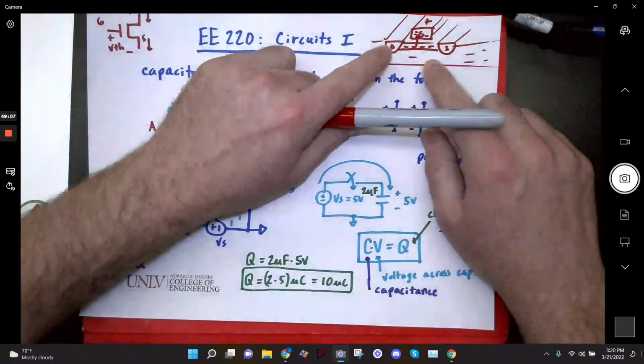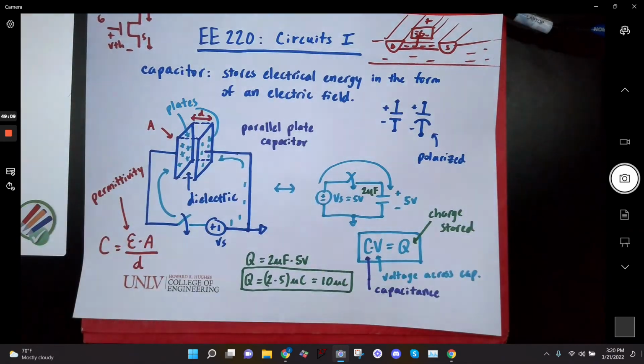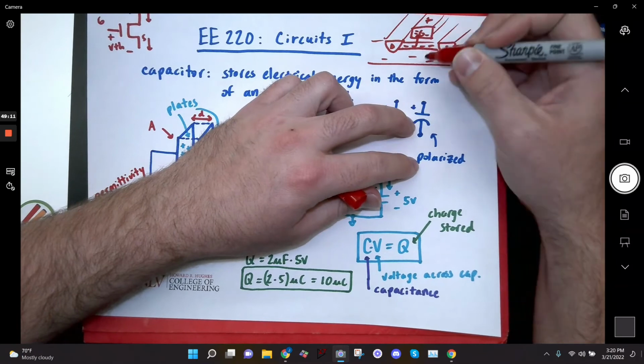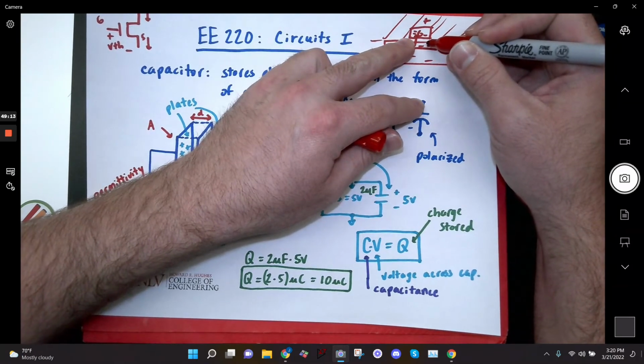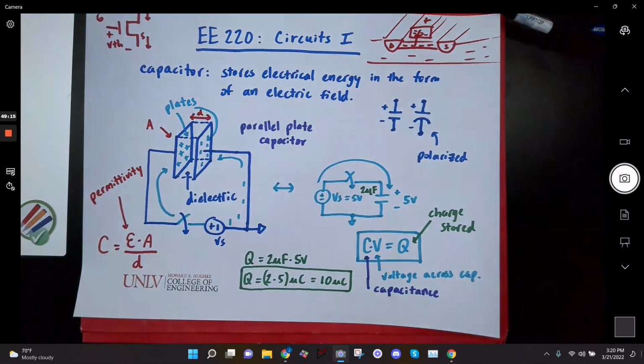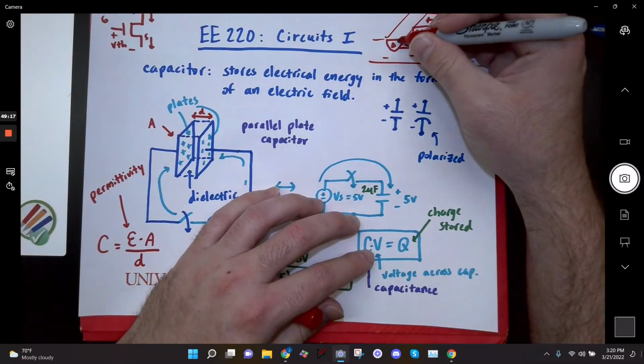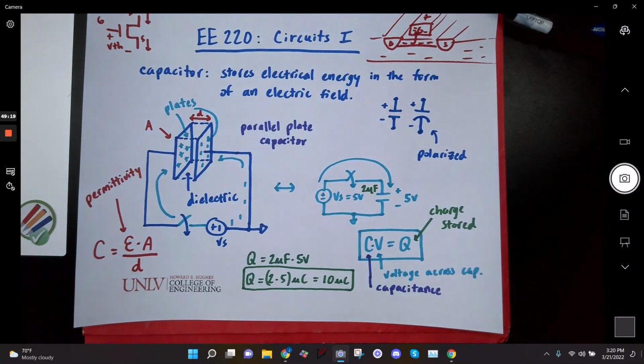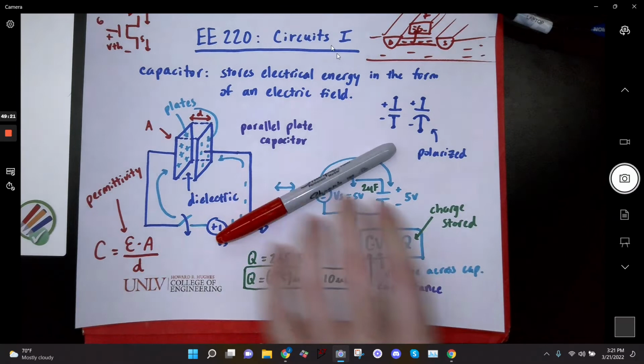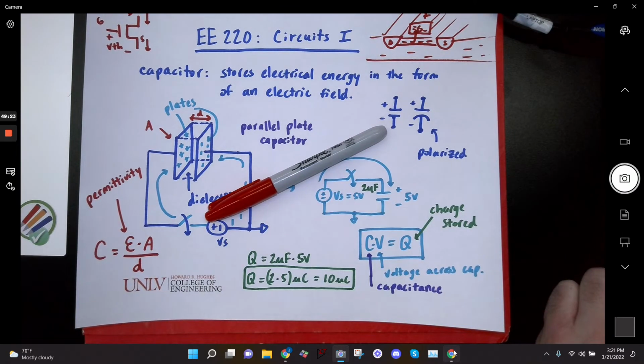You basically have all these electrons sitting down here, and the material's neutral, but when you put a voltage at this gate, electrons get pulled up into this region here, and now you have a channel of electrons where current can flow, right?